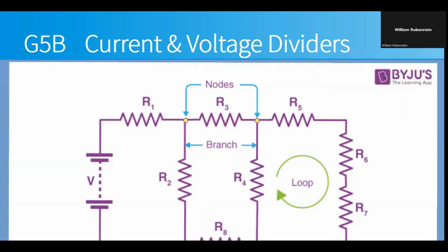It's a very complicated drawing, but if you think about this one, which is kind of a series parallel circuit, if I start over here, I've got these three resistors in this one leg that are in series. So the effective resistance in that leg is the sum of these three.